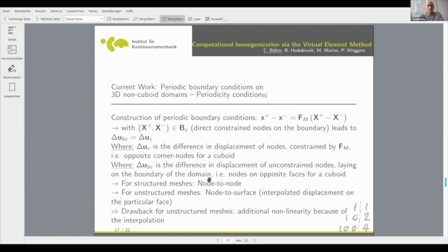It's something where you apply the load on the macroscopic framework and solve the computation simultaneously in the macroscopic framework and microscopic framework. For finite elements only, it would be FE squared. Okay, so for that, periodic boundary conditions are an advantage. Why? Because we know that periodic boundary conditions have a better convergence rate, and so the convergence rate would then influence our full convergence rate of the two-scale problem.